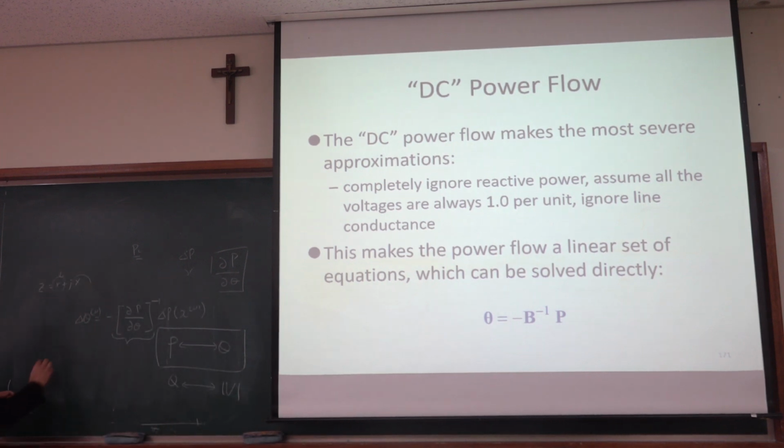So the heart of DC power flow, this is famous, is what? This computation: the computation of the inverse of this susceptance matrix. Then what is a difficult part here? Sometimes some components of this matrix B can be very small, and sometimes this matrix B is ill-conditioned. Anyway, we need to compute the inverse of that, so it can be sensitive to that.